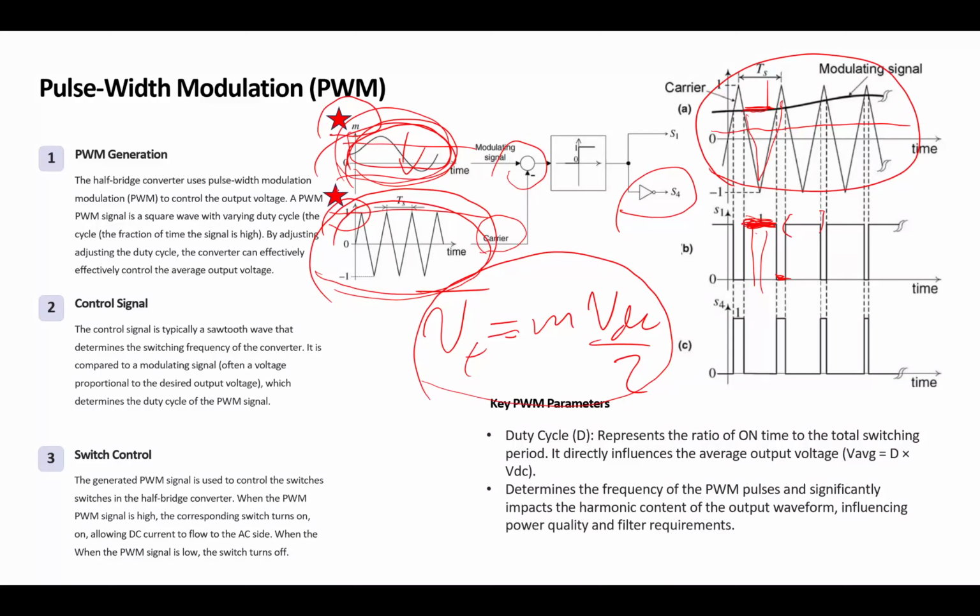What do you mean? If switch 1 is high and not. Okay, that's the result that I'm calling. We want to change this width, which is our duty cycle. One way is to go higher or lower in the reference signal. That way, we increase or decrease that duty cycle, because the duty cycle is the result of the reference minus that carrier.